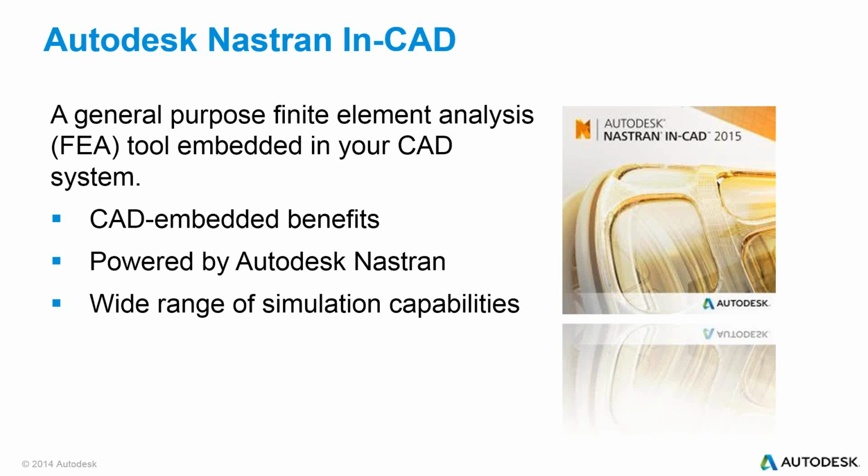It's embedded in the software, so those of us coming from Inventor Professional are familiar with the stress analysis and the dynamic analysis available here. You're going to see this right on the same panel on the ribbon, using Inventor as the preprocessor and postprocessor, with Nastran as the solver.